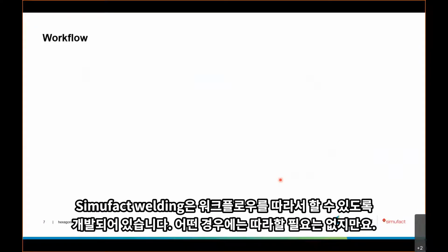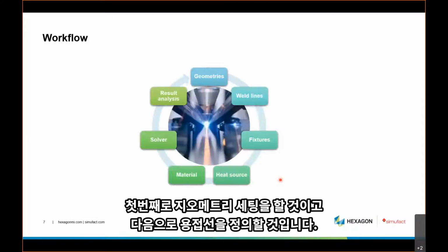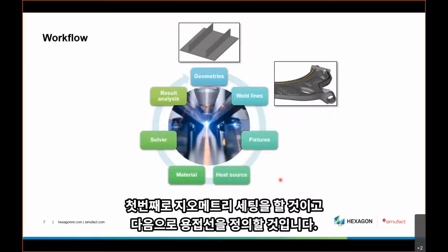Simufact Welding is also designed so that you can follow a certain workflow. You don't have to follow it, but it makes pretty much sense to follow this workflow. First of all, you set up your geometries. And the next step, you define your weld lines.